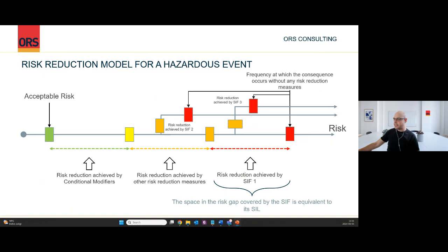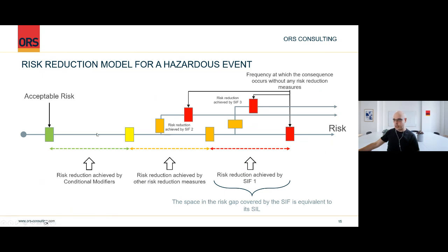I tried to explain this graphically, right? In the previous one, we had one line. Now we have maybe 3 or 4 different lines which are protected by different safety instrumented functions. At that point, LOPA becomes a little bit too one-dimensional for this problem. So when you find something like this, normally LOPA is not going to give you a full answer, and it's not going to give you a really detailed answer. So for cases like those, you need to do fault tree analysis, right?